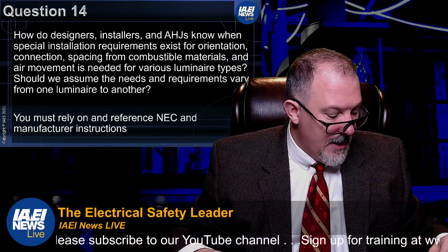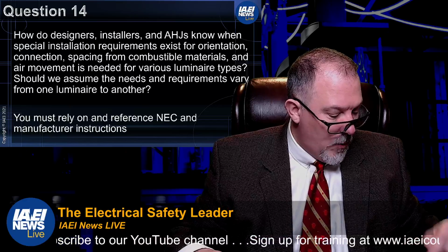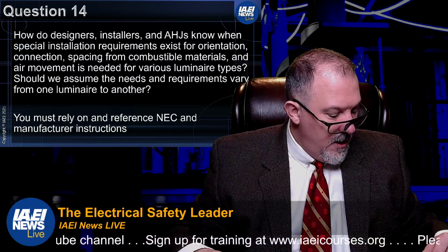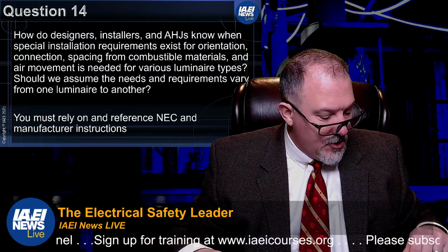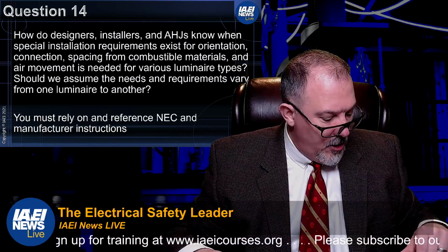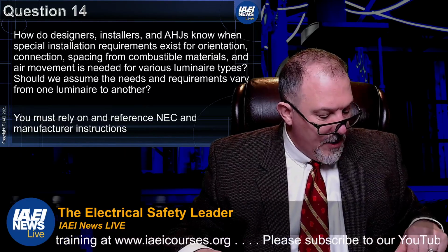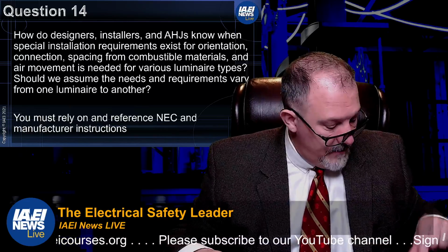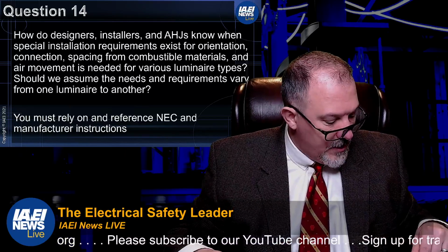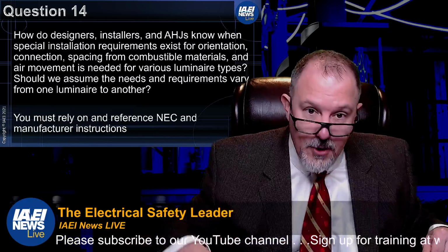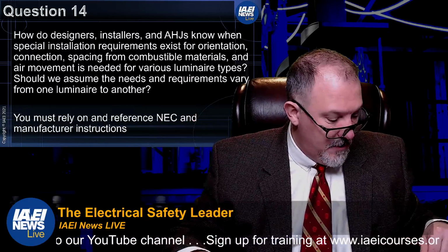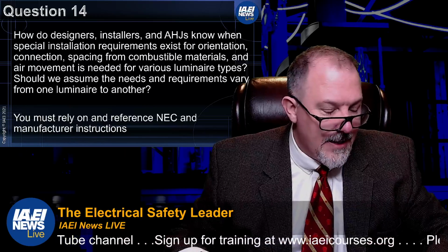Let's keep going. Part 9 is lamps and auxiliary equipment. 410.104 says electric discharge lamp auxiliary equipment shall be enclosed in non-combustible cases and treated as sources of heat. So 410.104(A) is another reference, right? And this is based on various luminaire types. Part 10, let's take a look at Part 10.